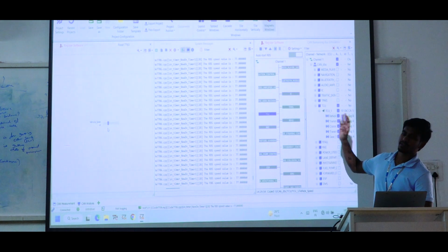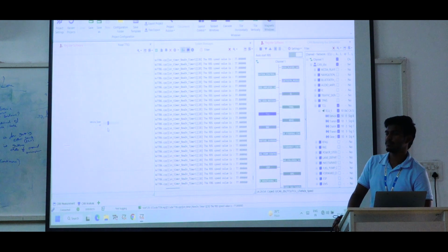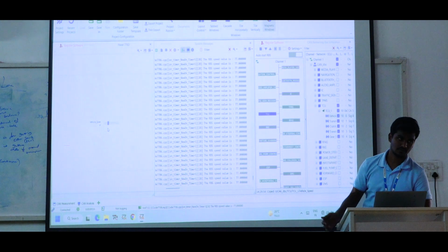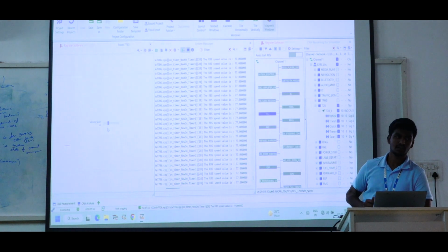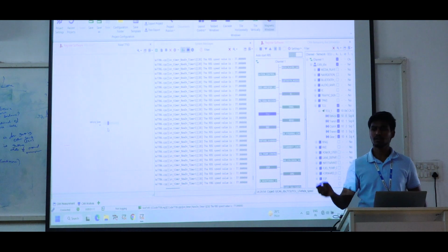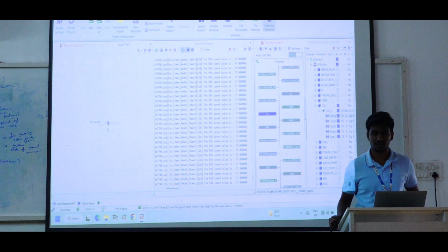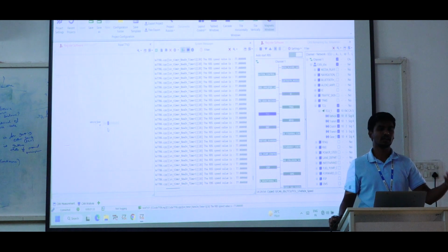Why I am explaining with this track bar and everything is that our next requirement is a seatbelt logic. For the seatbelt logic we need to receive some values. For example, I have only one condition for seatbelt. Suppose you are not wearing the seatbelt and your vehicle speed is greater than 20, then we need to give an indication for the driver system. Give some beep sound and then LED indications. So first we need to get some values from vehicle speed. What is the vehicle speed now? It is 10 km per hour, 20 km or greater than 20 km.